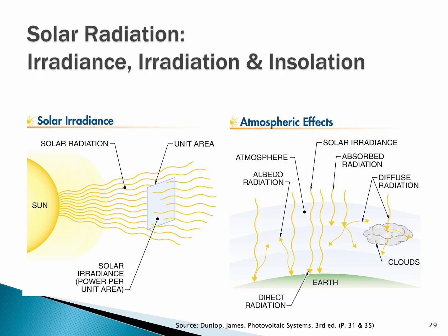That solar constant is 1,366 watts per meter squared. So as the solar resource filters down through the atmosphere, bouncing off of water droplets and vapor and pollution and whatnot, we lose about 366 watts in its journey down to sea level.